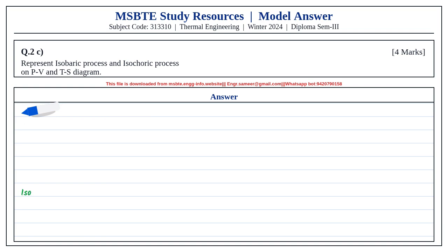Impulse turbine is used for high head and low flow rate. Reaction turbine is used for medium head and high flow rate. Impulse turbine has symmetrical blade profile, while reaction turbine has non-symmetrical blade profile.